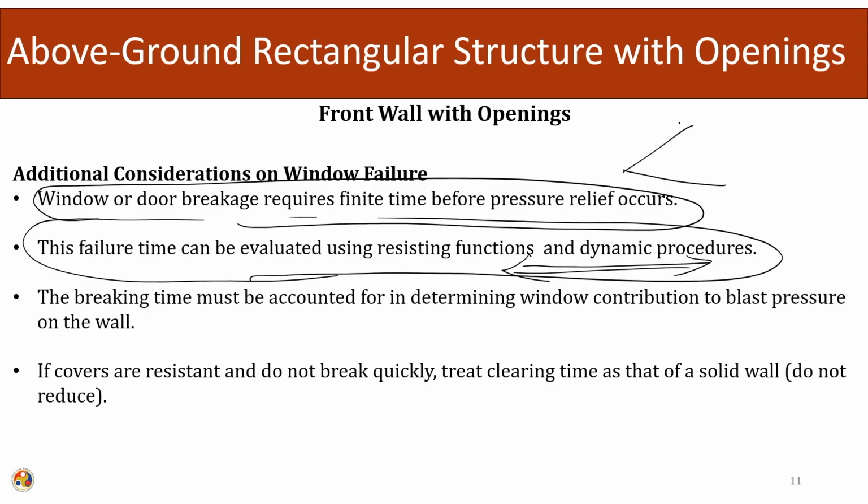Meaning, what is the dynamic loading on the structure, what type of failure it is going to cause, whether it is going to cause a bending failure, shear failure, or a bearing failure, brittle type of failure, or elastic failure. So, this will depend upon the resistance mechanism as well as the loading mechanism. If we know both of these things, we can analyze how this will occur, but nonetheless whatever happens, some time will be required for this mechanism to engage.